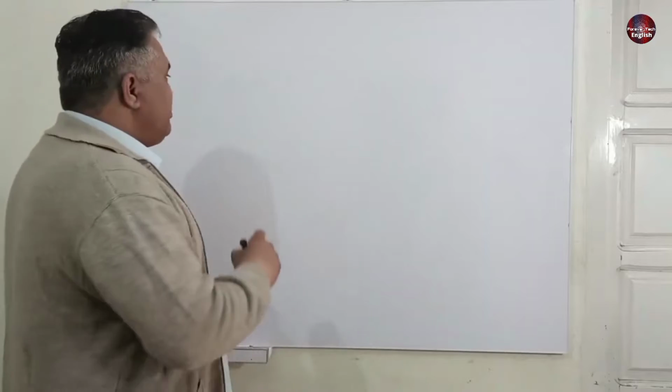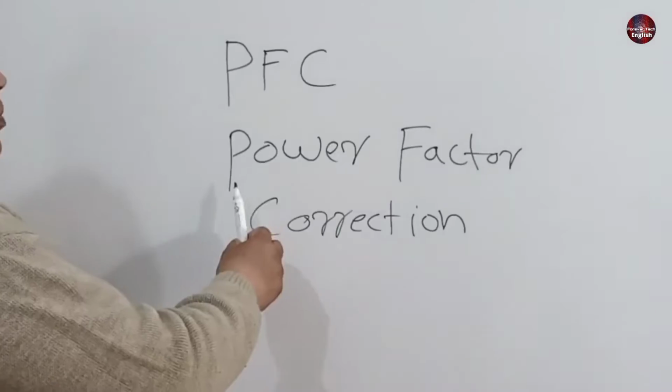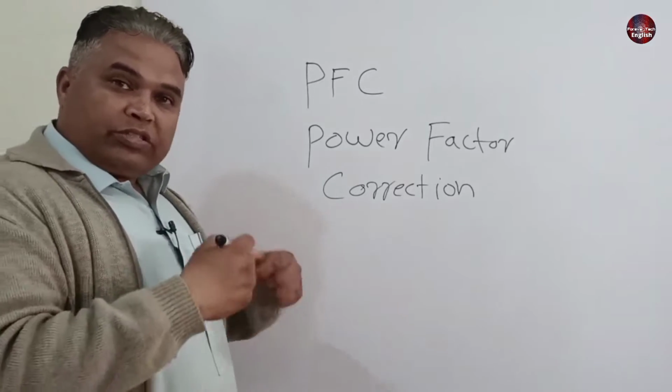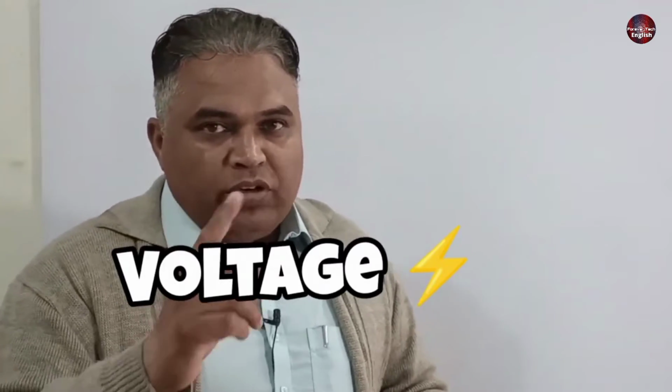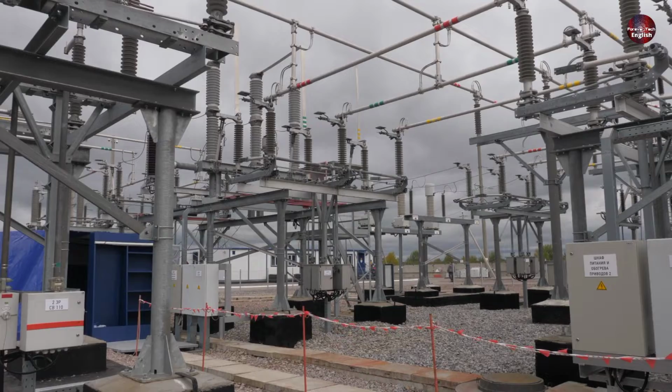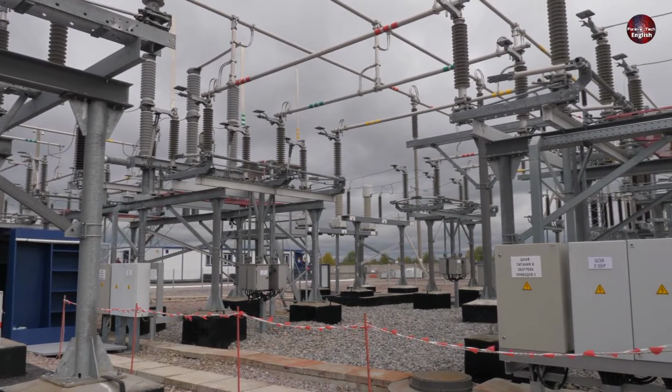Basically, the two IGBTs are used to make the PFC, or power factor correction, better in the inverter boards, resulting in more efficiency. The power factor affects the voltages and the current. The current is more important. Due to a good power factor, the power loss in the electrical equipment decreases.